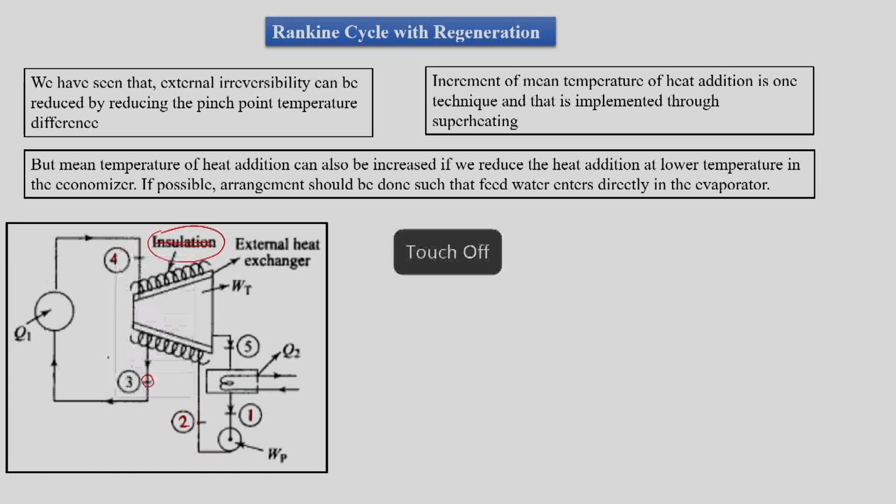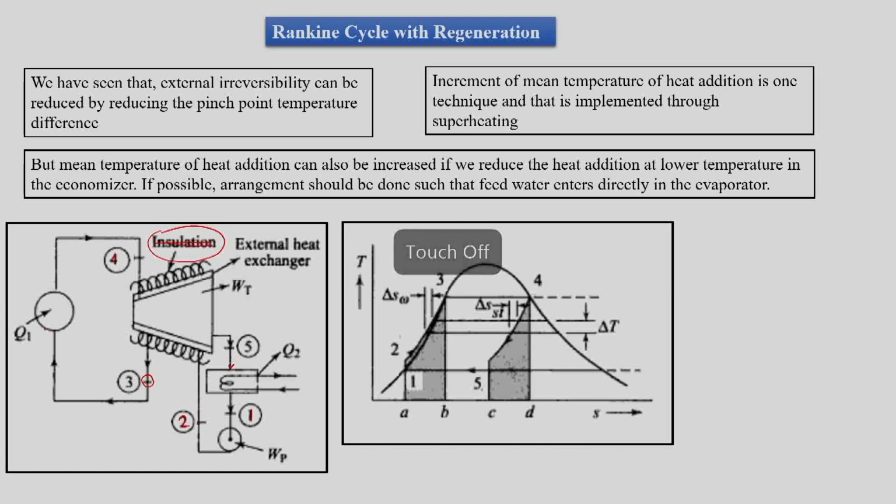It will have the latent heat added in the boiler or steam generator, and then the dry saturated or superheated steam will get expanded in the turbine and come back to the condenser. This is a thought experiment. In this thought experiment we expect that 1 to 2 is the pump work, and 2 to 3 is the heat getting transferred from the turbine.